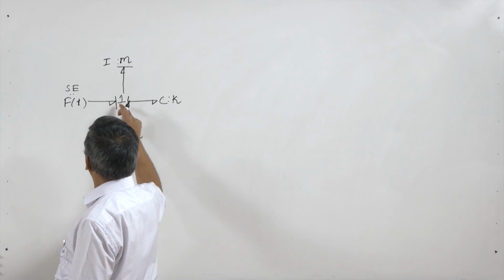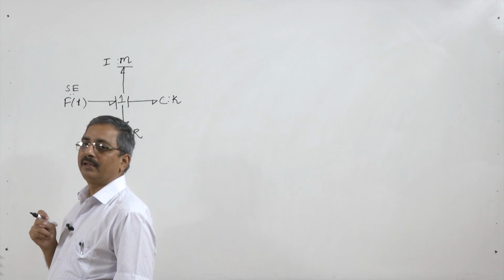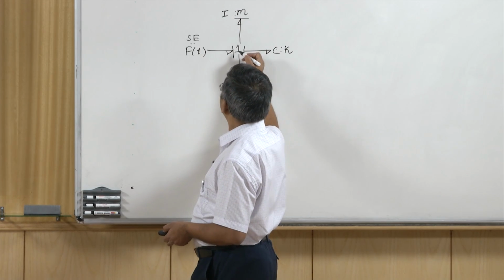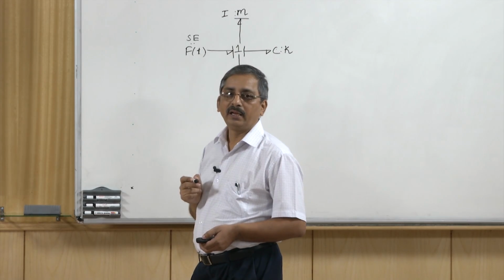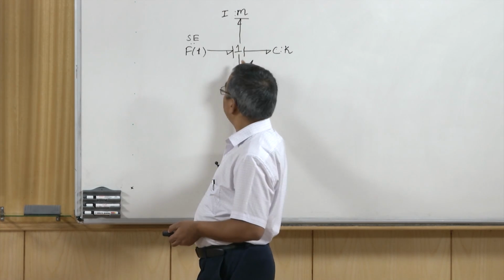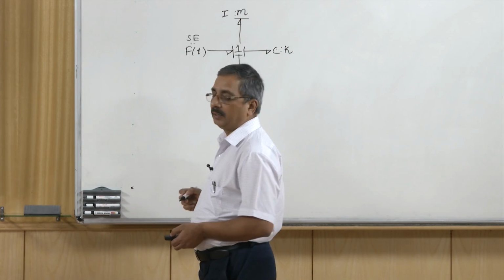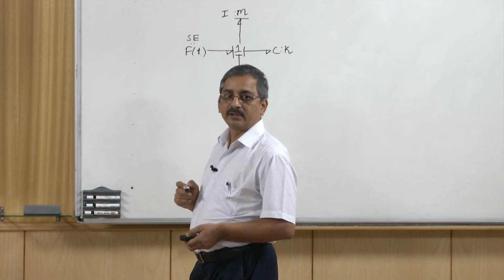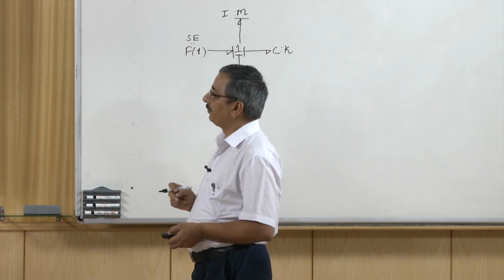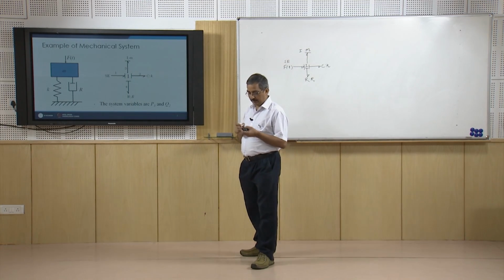Now, this junction is a constant flow junction. So, if you look at the causality of the junctions, then we can see that this flow has to be decided by any one of the bonds, and I is already doing that. It means that the R here is going to have the stroke here. Okay. So, that is, the R element will be giving the effort to the junction. So, this way we can create the bond graph for this system.